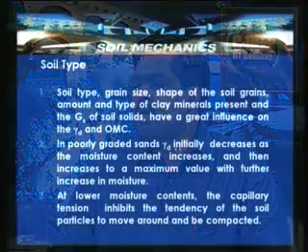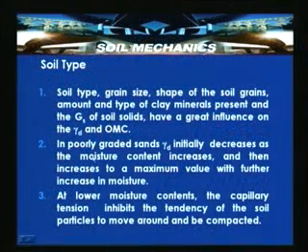So, in poorly graded sands, the dry unit weight initially decreases as the moisture content increases and then increases to a maximum value with further increase in moisture content. At lower moisture content, the capillary tension inhibits the tendency of soil particles to move around and be compacted.